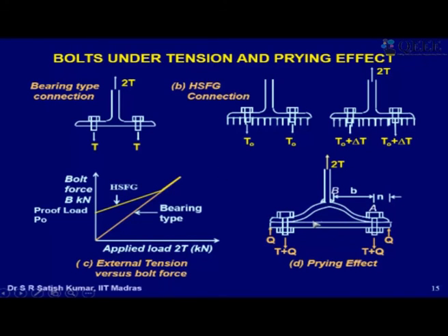So basically, what happens is prying force is nothing but something similar to, you must have seen carpenters pulling nails out of wood with what is called a prying hammer. Okay, so the hammer has like two tongues. You put each one around the nail, so the nail is caught between these two, and then instead of pulling the hammer out, you press the handle down, right? What you do actually is you pry the nail open. Okay, that means if I have a plate like this, I'm showing in the slide, and if I'm pulling this up, the lever, with 2T, then I would have expected a force of T in each bolt.